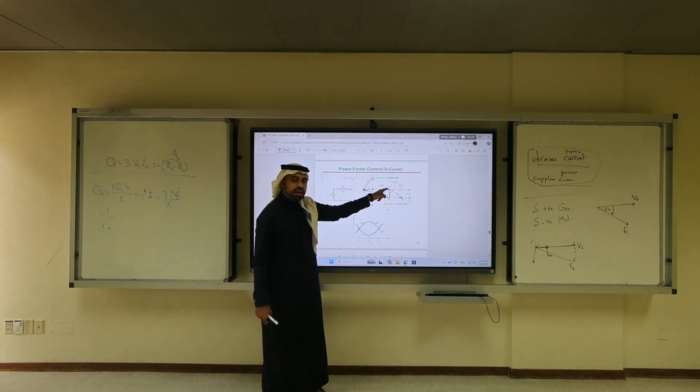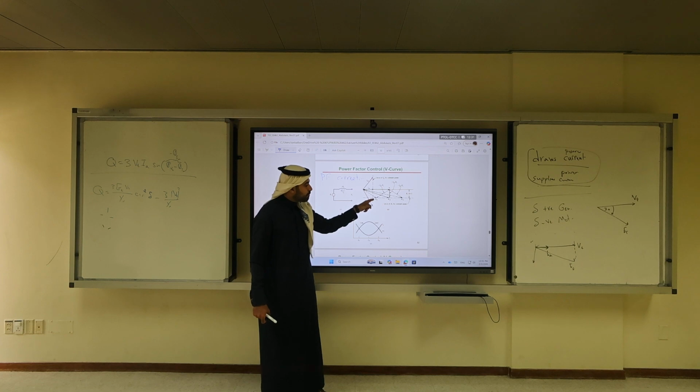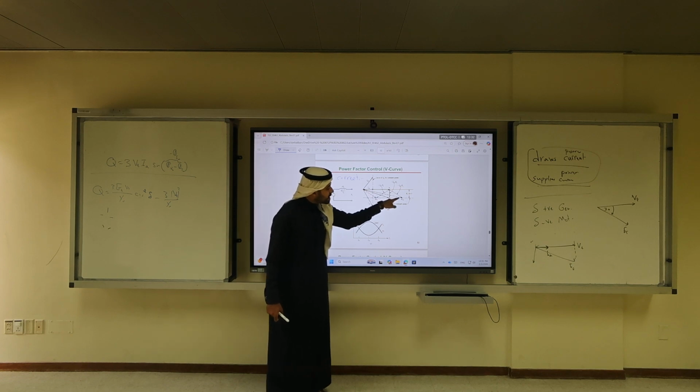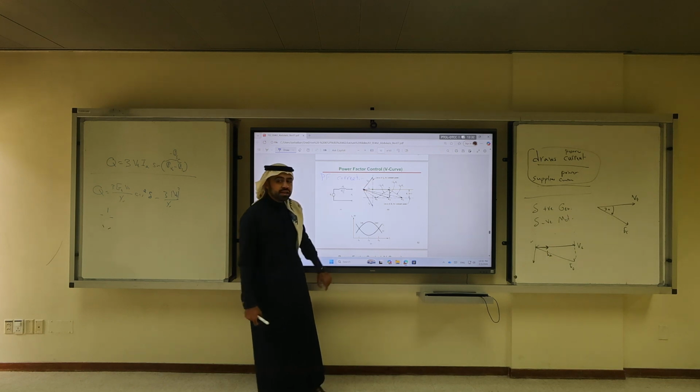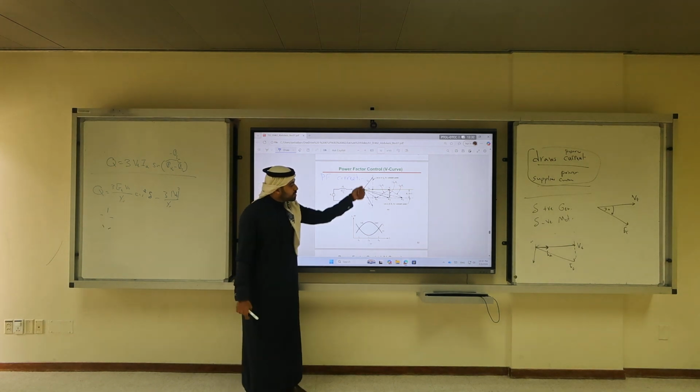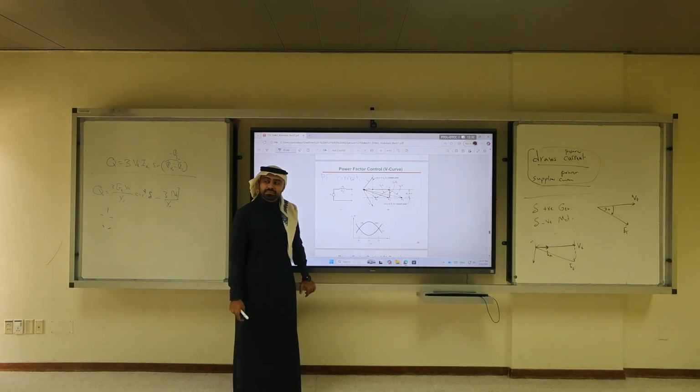In the motor, am I maintaining my VT? Yes, from the infinite bus. So I can change the excitation EF of the motor by only changing the power factor. By increasing EF2, I can make my power factor between IA and VT unity. If I increase the excitation, EF3, I will have IA3 leading. Thus, I improve my power factor, and this would act like a capacitor.